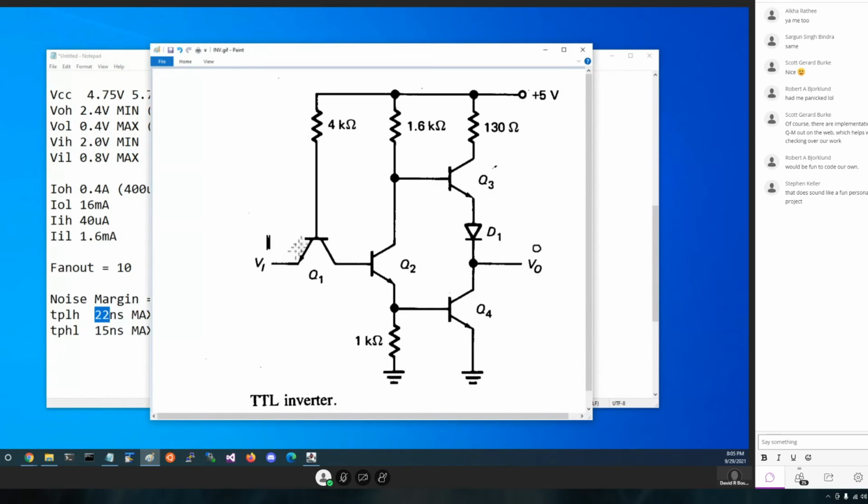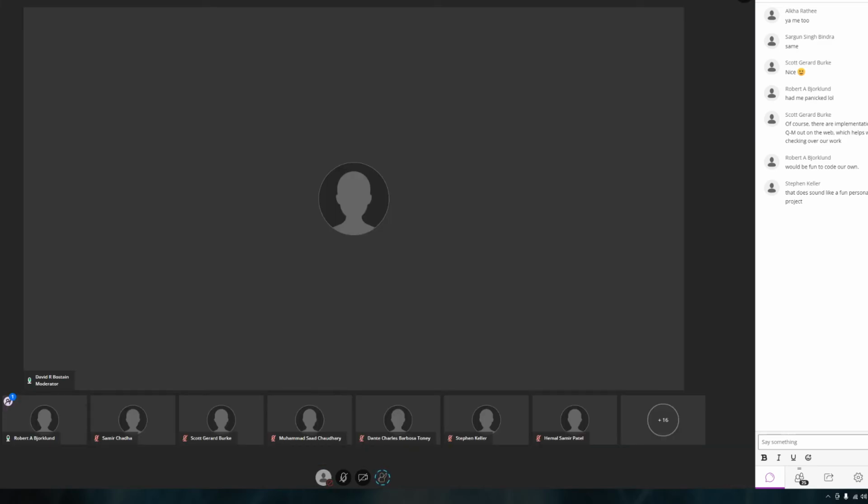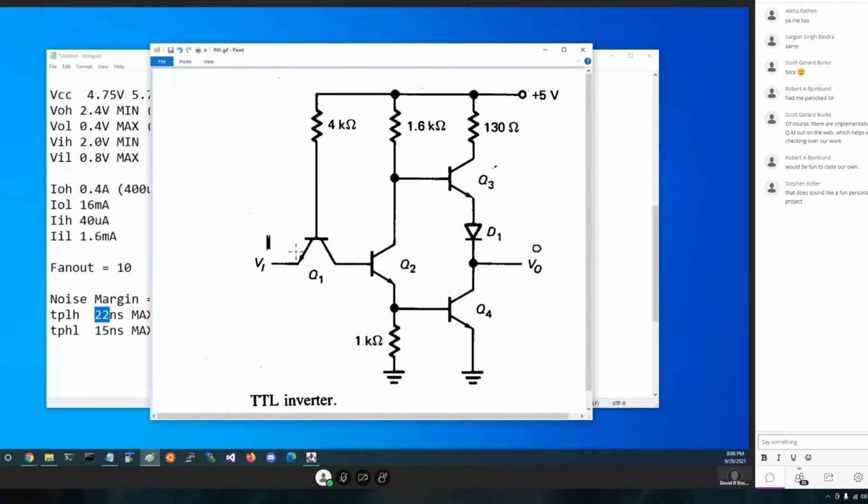Okay. So if we have 5 volts on the two sides, the base and the emitter, Robert, tell me about that. Is that going to turn it on or off? I think it's going to be cut off because the 5 volts does have some resistance there. Right. And this also probably not really completely 5 volts, because remember we said that it might only be as high as 3 something. Right. But there's not enough to get 0.7 volts there, which means this transistor is off.